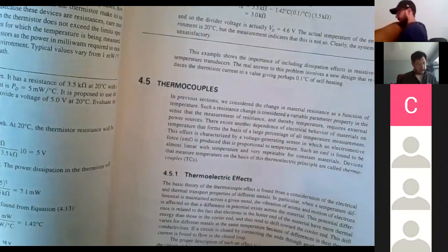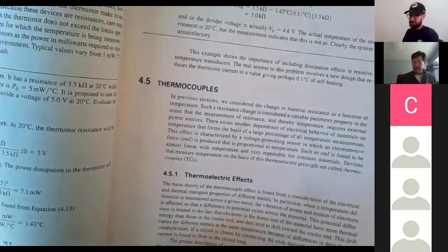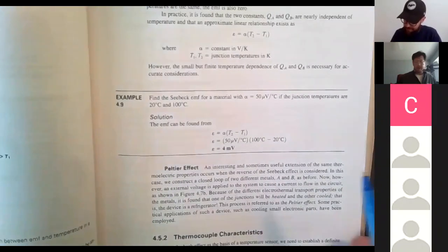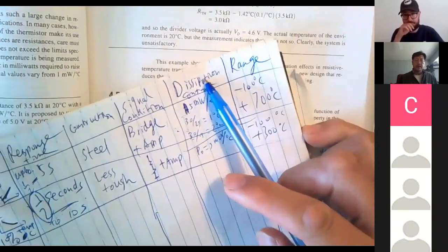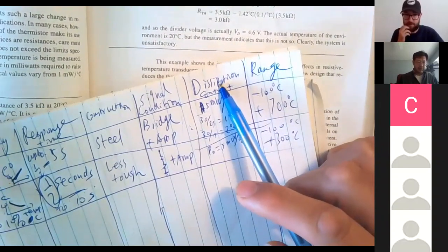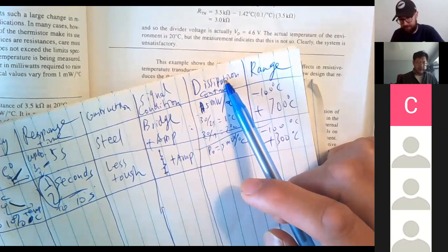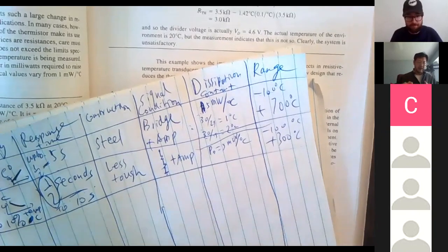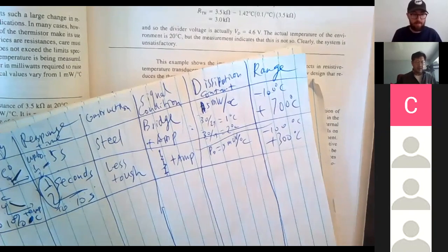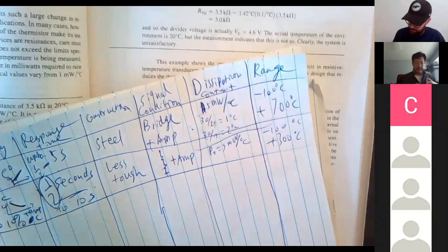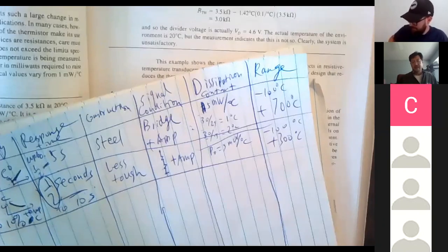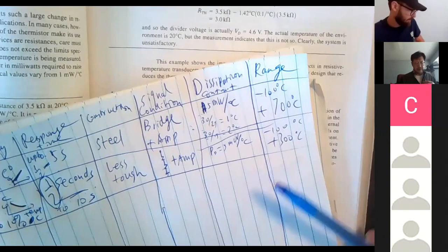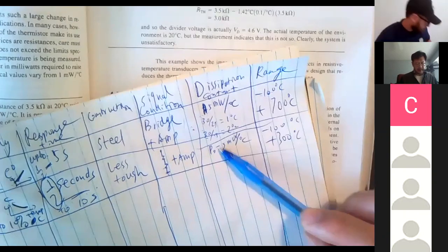All right, so that's a problem. Self-heating is always a problem. How do we reduce the self-heating? The self-heating can be significantly reduced if you have a good heat sink. So you do not have your sensor in a very closed environment where that energy cannot be released to the environment. So that can be reduced.